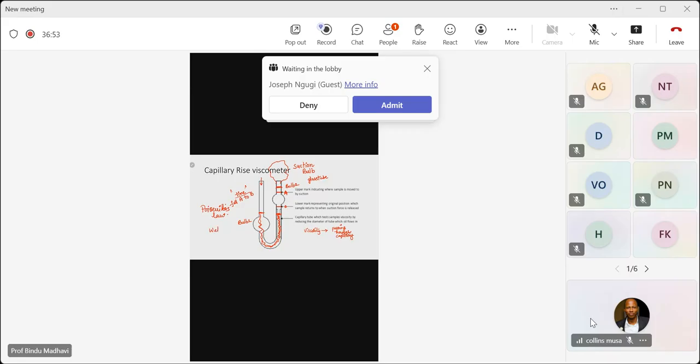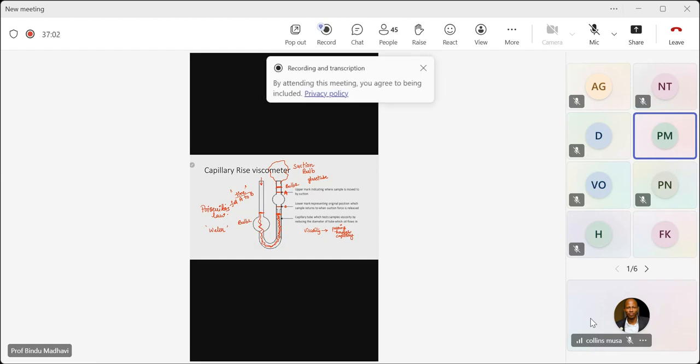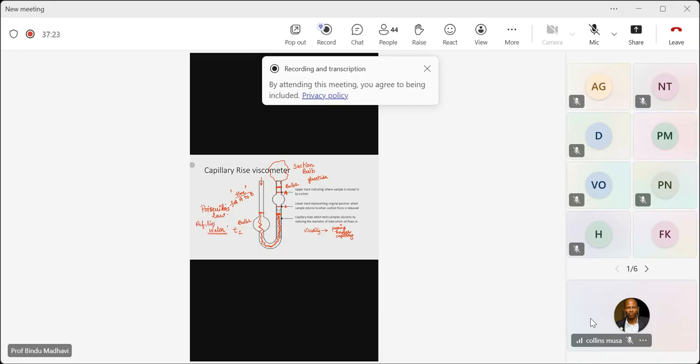So what we are going to do to measure the viscosity is first measure the time taken by water to fall between A and B. We maintain the conditions and everything standard. Initially we take water, conduct the experiment, and note down the time taken by water to fall between A and B. Water is considered as the reference liquid.